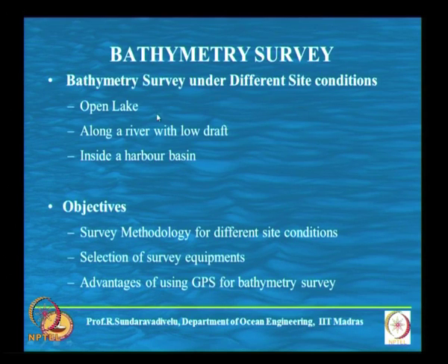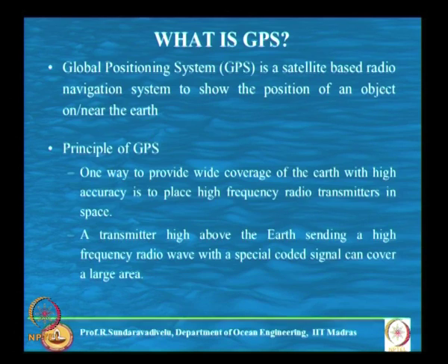Apart from location and communication, we now go into the technical requirements, that is, the bathymetric survey. It will be done for different site conditions: on an open lake, in a river, or inside a harbor basin. In each case the bathymetric survey is slightly different. We will discuss survey methodology for different site conditions, selection of survey equipment, and the advantages of using GPS for bathymetric survey. Now we will see what GPS is.